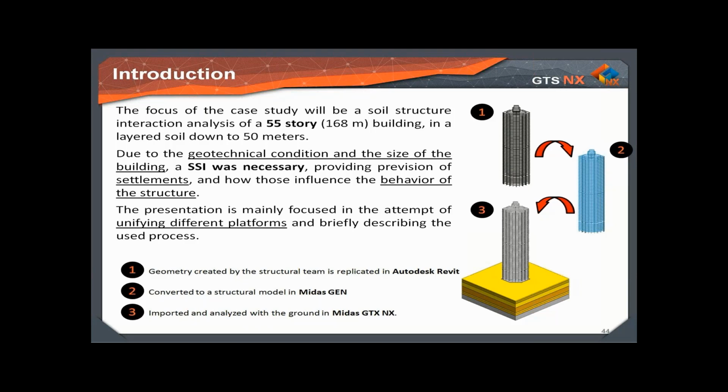With the Revit MIDAS Gen link, the structure model was exported to MIDAS Gen, and after applying some conditions from Gen, the model was finally exported to MIDAS GTS NX, where the full model with the ground was analyzed.